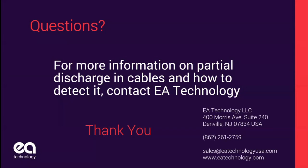Could you please talk more about the safety concern when using the RFCT? Sure. RFCTs, we're attaching them to the ground, and you would think that is 100% safe, but there are a couple of considerations you need to worry about. One is that the ground strap itself cannot part. The highest fault current that you might detect through the shield cannot be more than that cable can carry.